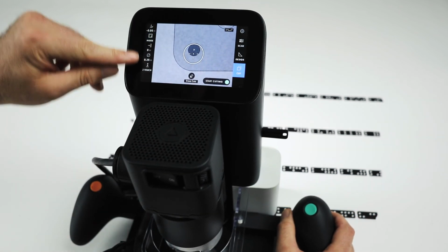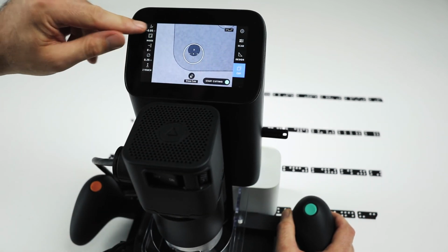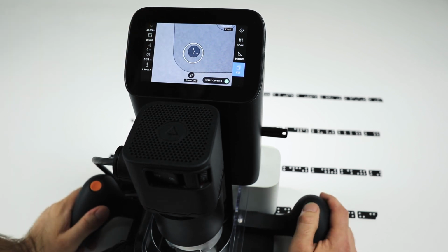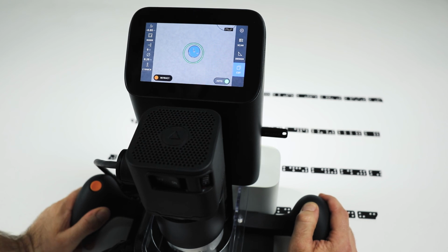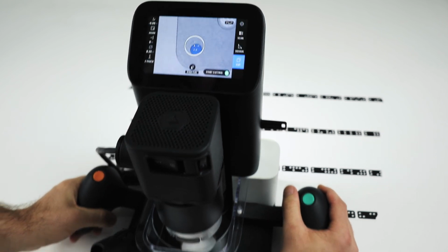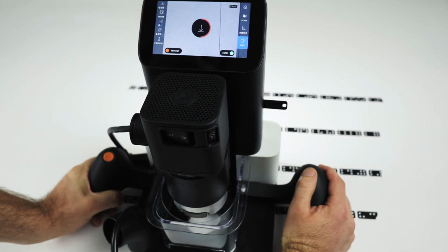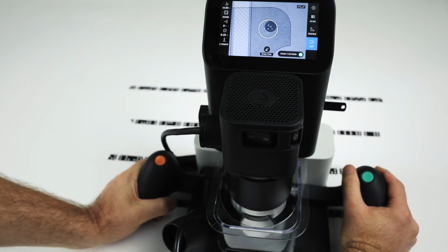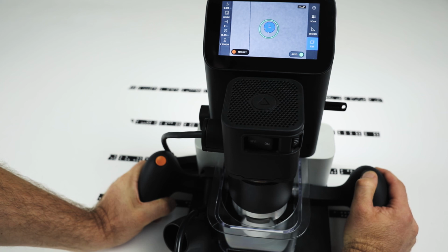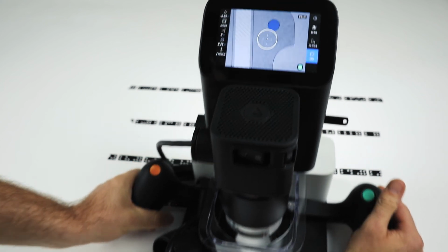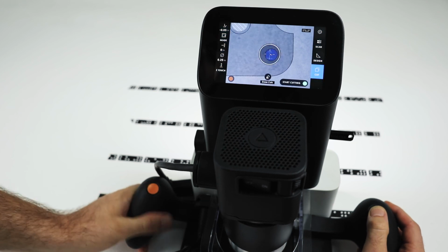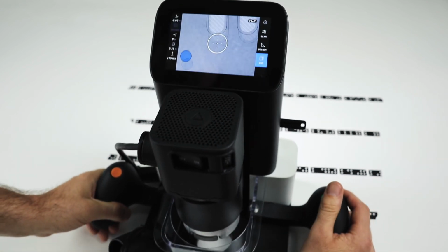So we have a 1/4 inch cutter, and we're doing an air cut. So we're hovering above the surface. So I'll just quickly show what we're dealing with. Holding down auto, we cut that hole. So you do the small interior details first, and then you cut the whole thing out as the last step. So I'm going to do these little circles. And then we'll do the pockets.